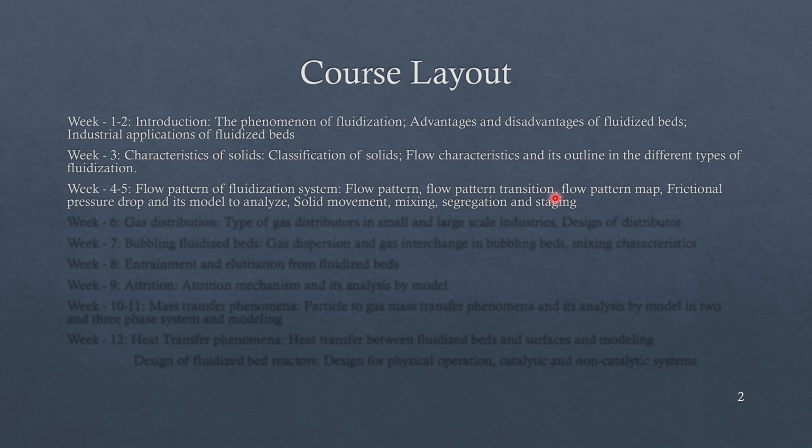When we are passing the gas inside the fluidized bed, the particles rise, and with some excess, small bubbles start to form. This is known as the bubbling regime. With time and with increase in velocity, the bubbles grow in size and reach the size of the column.